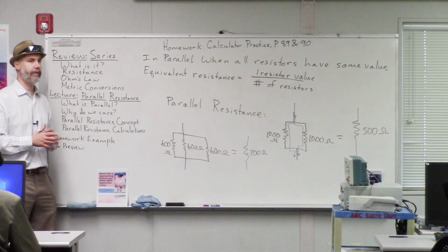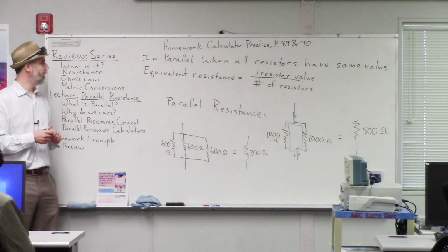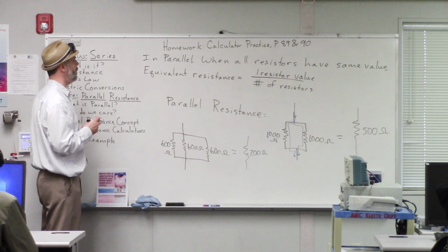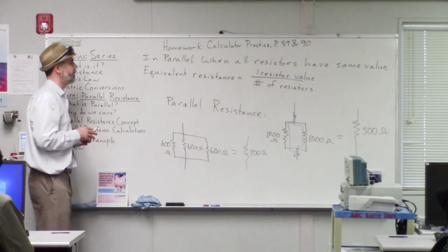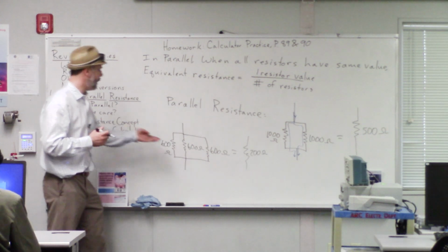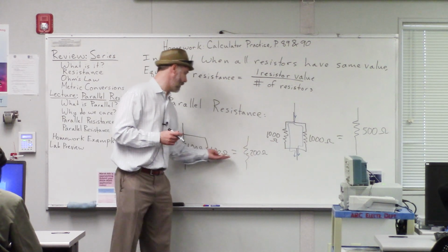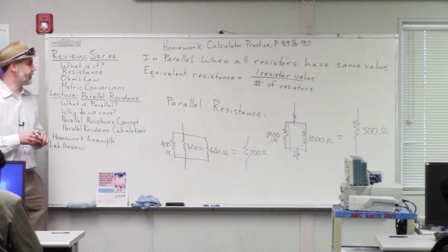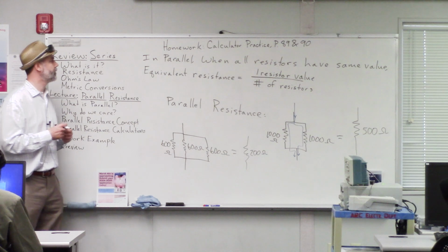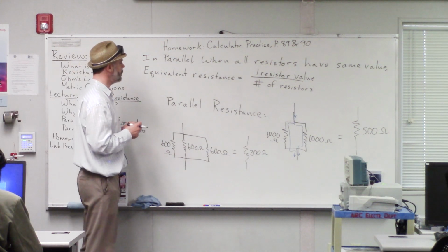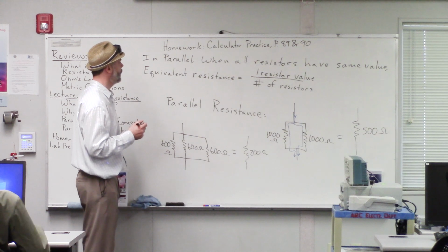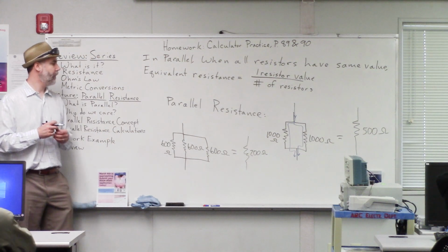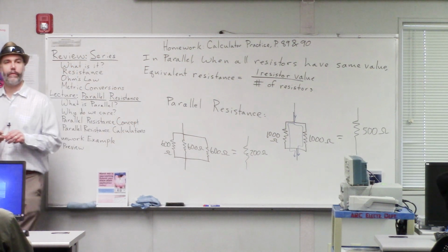So, questions about that? And another thing about parallel resistance, no matter what, the total resistance is going to be less than the smallest single resistor. So that's for all parallel circuits. So, any questions about that?